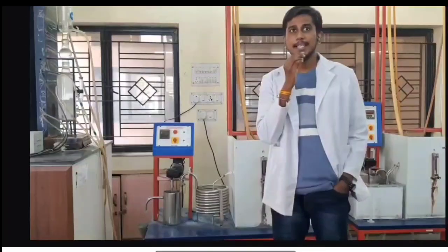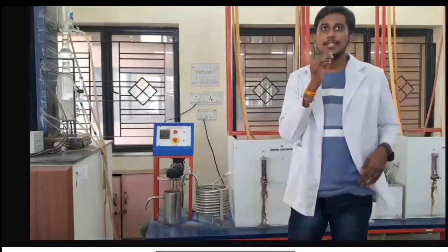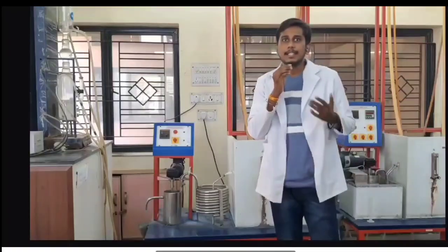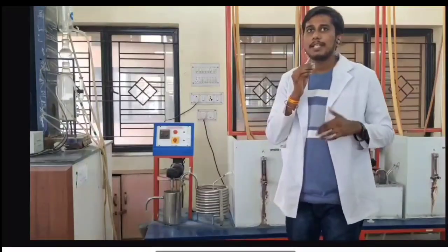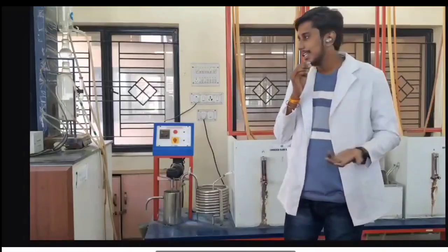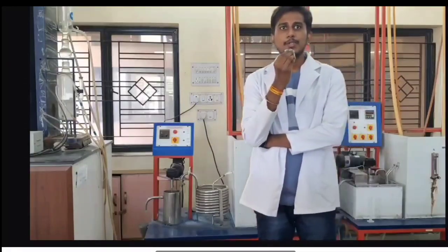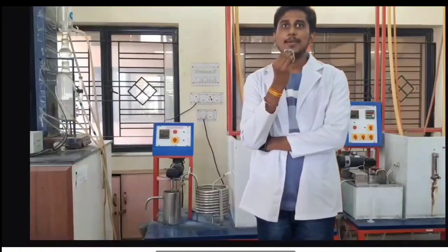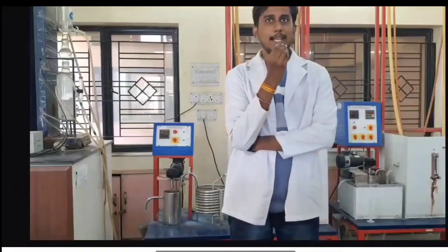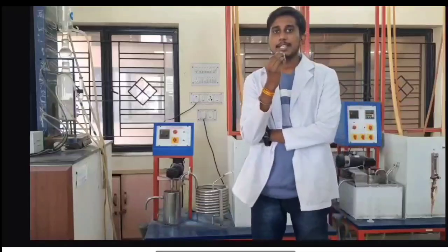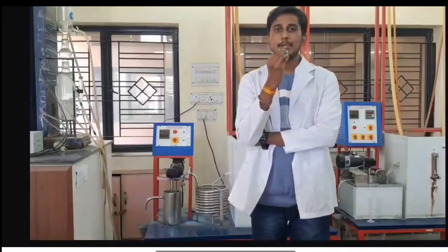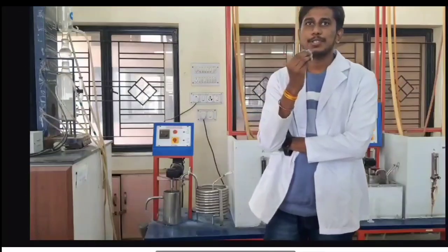For instance, in the CSTR, the reactants continuously mix with the content inside, while in the PFR, they flow in a more orderly way, like plug flow. Now, adjusting the flow rates with the rotameter. Each rotameter ball allows us to regulate the flow of NaOH and ethyl acetate. We need to check the readings carefully and adjust slowly to avoid any overshoot.